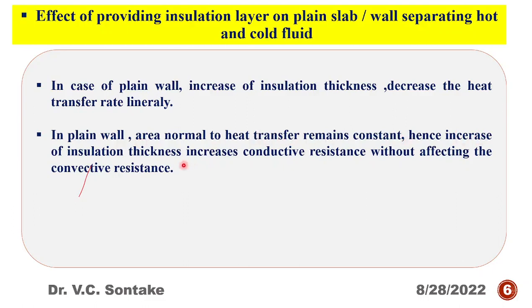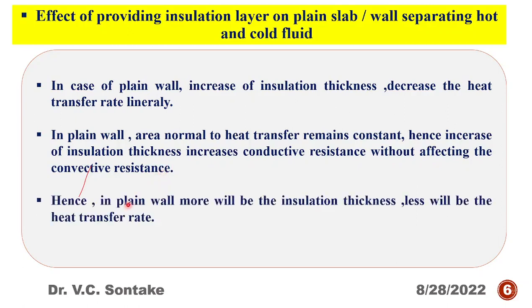Hence, increase of insulation thickness increases conductive thermal resistance without affecting the convective thermal resistance. So as the conductive thermal resistance increases, heat transfer rate decreases. Hence, in case of plane wall, the more the insulation thickness, the less the heat transfer rate. This is the conclusion I can draw from the analysis.